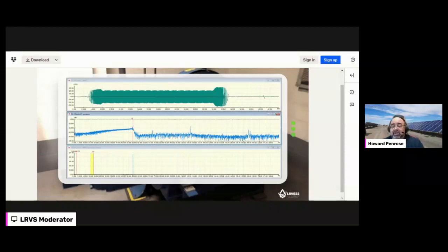As you can see in the middle slide, the conversion of that signature from 0 to acceleration to constant speed to deceleration to 0 again causes that slope that you see in the middle signature, which is my FFT of the current signature in decibels. We'll be counting from the top of the line frequency down to whatever the peaks are. But you see that slope. That's because that line frequency has gone from 0, slid all the way up, and then all the way back down again. Well, what can I do about that?